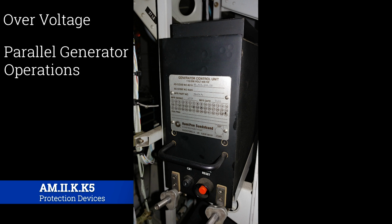Paralleling is typically found on a little bit more complex GCUs. The most modern aircraft are multi-engine, and a GCU basically helps coordinate the parallel generator operations. So a paralleling feature has to be employed to ensure that every generator in the system is operating within limits. In general, paralleling systems compare the voltages between the two or more generators and adjust the voltage regulation unit accordingly. That way everybody is on the same page, and you don't have one generator that's overproducing or another one that's underproducing, and so on and so forth.